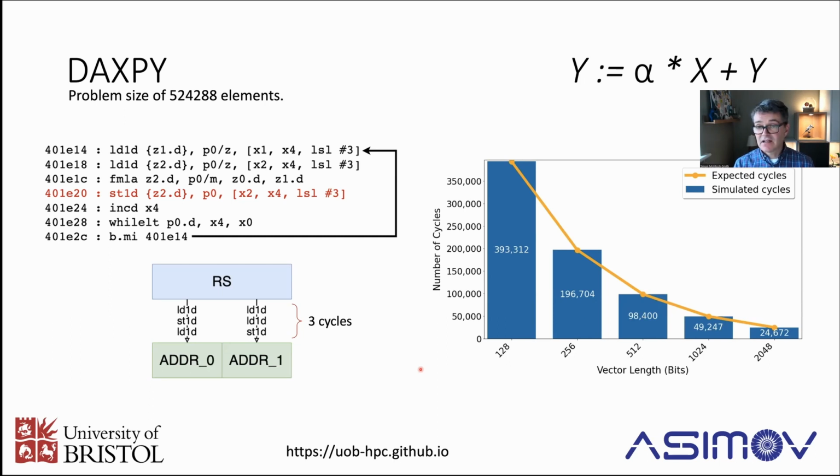And then you just build a standard ARM binary. And like I say, today, if you use GNU or the ARM compiler, that should be fine. You tell it to build a static binary, and there's a special flag you give it to do that. And that's all you need. And then you just run that binary through the simulator and off it goes. And then you can tell the simulator what you'd like to know about what happened. So you can tell it what kinds of output you would like to see, what kind of information, what kind of performance counters you would like from the simulation. But it should be as easy as that. And there should be some fairly straightforward instructions on the website for the simulator as well.